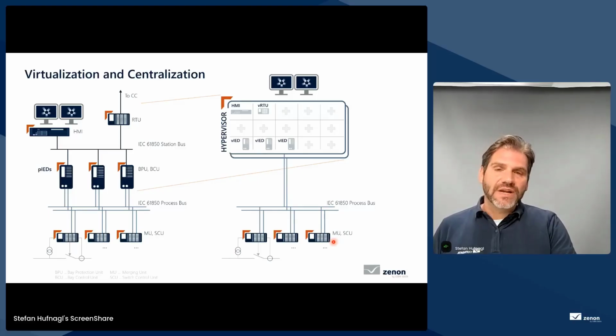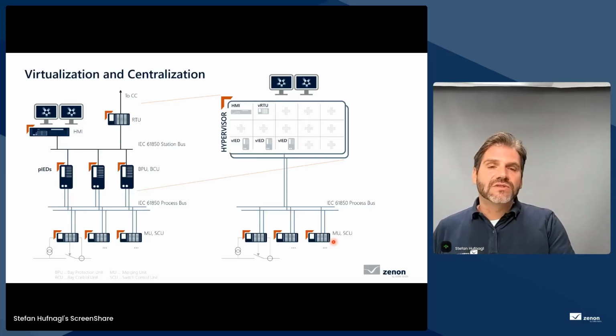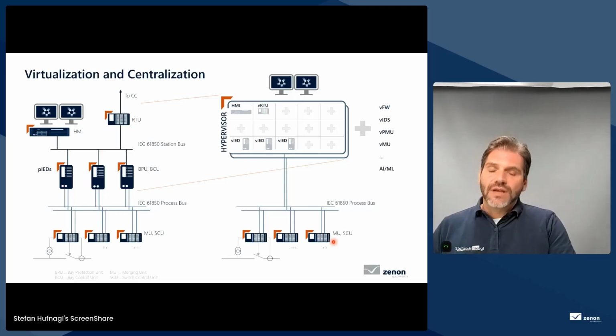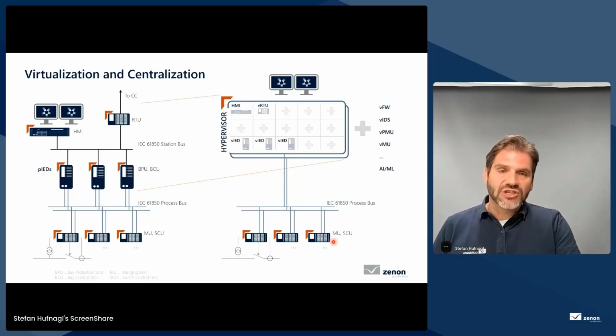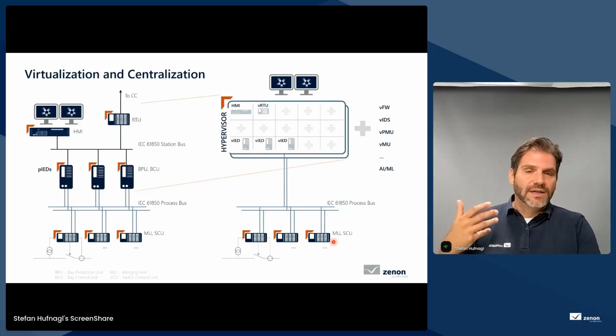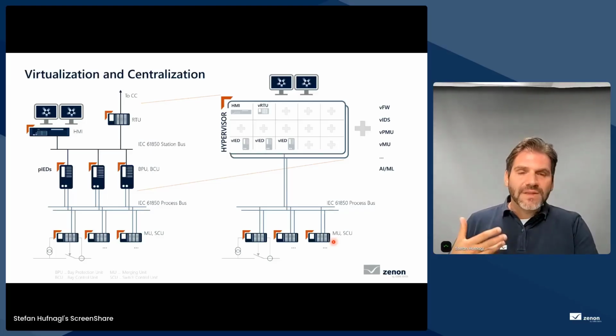And as we see already in this rough scheme, the number of hardware devices, the number of hardware instances could be drastically reduced. Additionally, other applications, other functionalities like security, firewalls, intrusion detection systems, for example, but also virtualized instances of a phasor measurement unit, for instance, or a virtual merging unit could be deployed and operated on